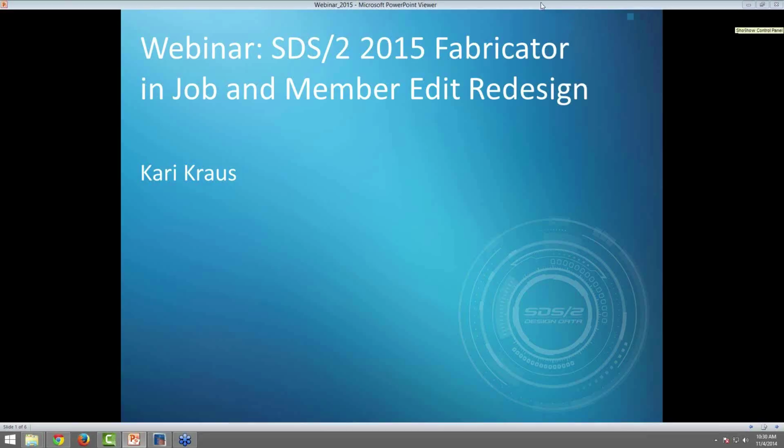In version 2015, the path to follow to find the fabricator: you find the 2015 data directory, the jobs folder, and then inside of the fabs folder. The Fabricator folder is still inside of the data directory. You can find this path by going to the 2015 data directory and then the fabs folder. This folder is strictly used for converting and storing fabricators. This will be discussed a little later.